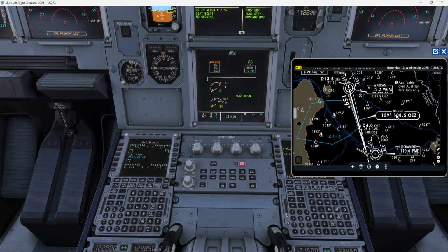This one is for the ILS DME, and course 159. No, 159 for this one. It's going to insert it automatically, so let's just leave it there, and then we double check because it's saying mismatch. So let's leave it there, and then we insert the radio nav. So let's skip it right now.